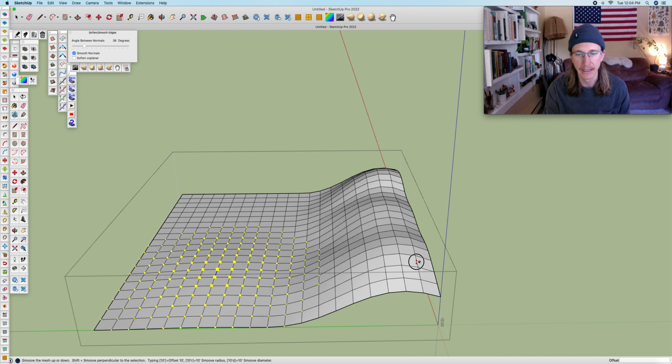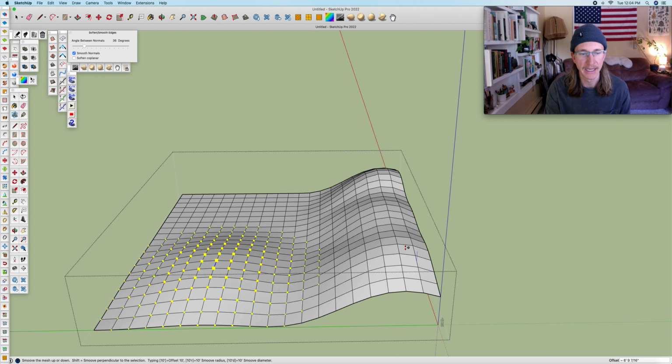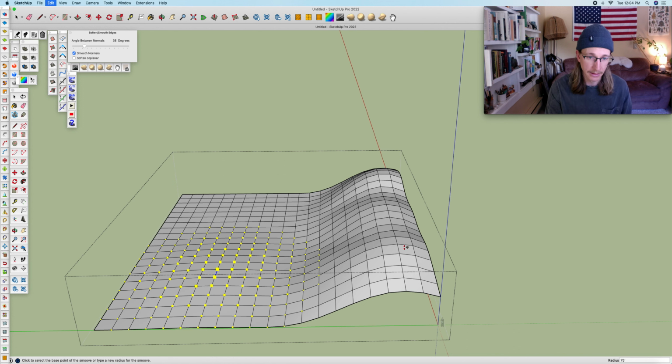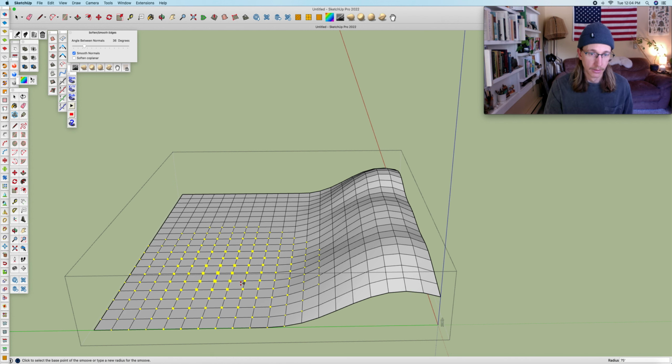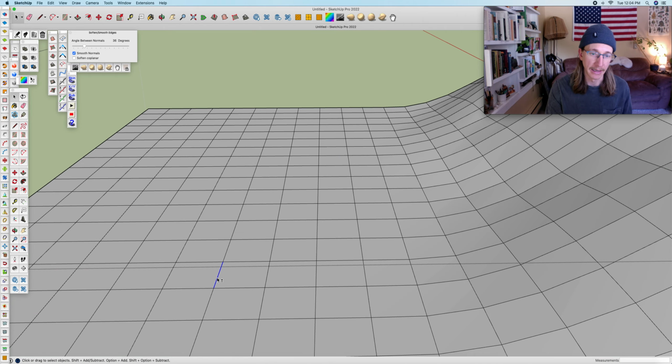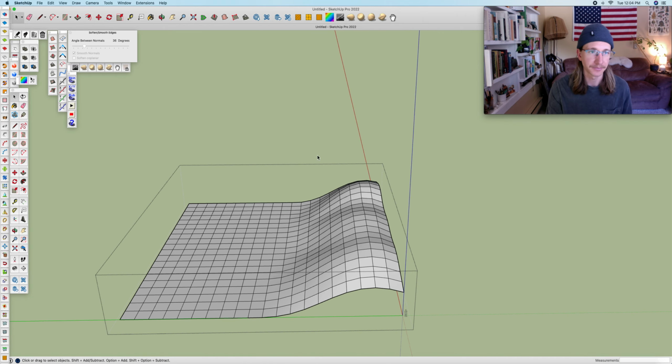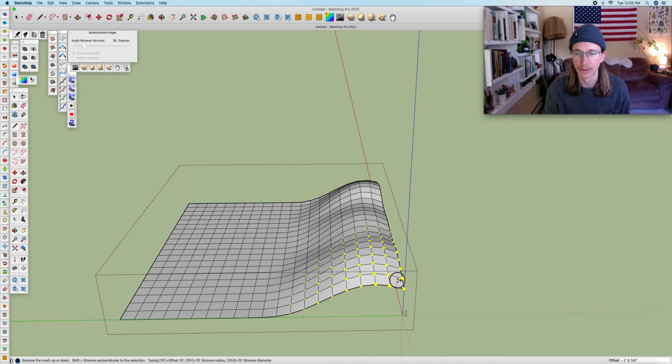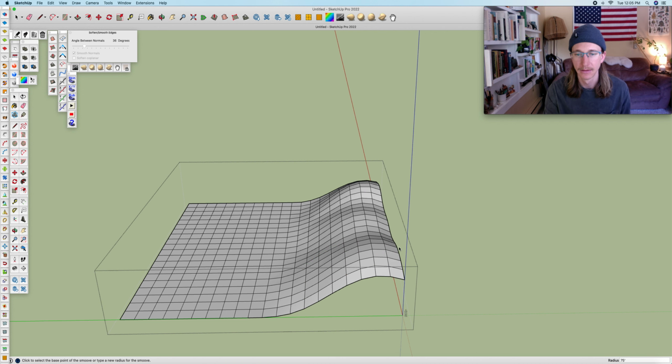And even if I'm clicking here on the right, I will remain tethered to that point, which is more than annoying, but the way to get around it is to just come and deselect it. And then when you come back to this topography push-pull tool, you can click where you want to move and do the function that you're after.